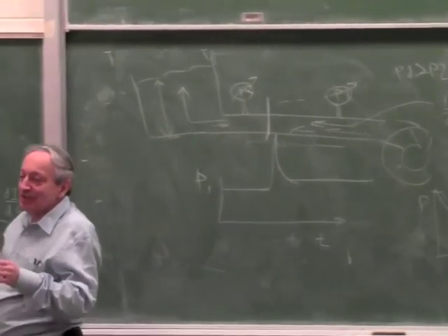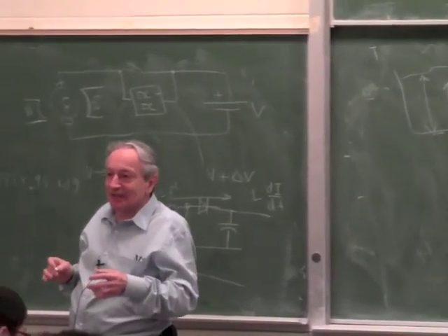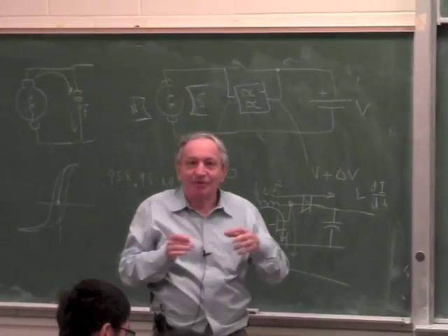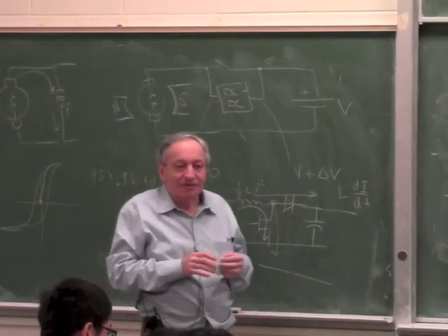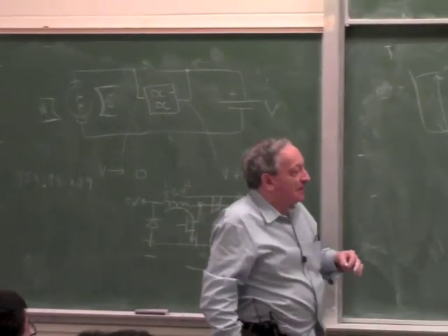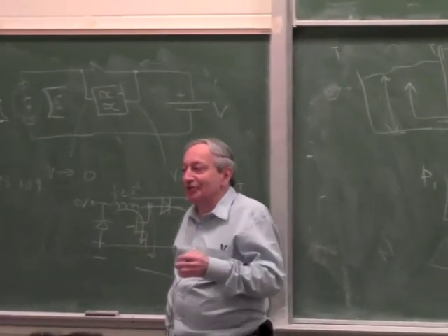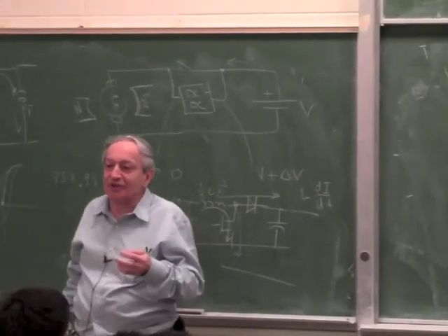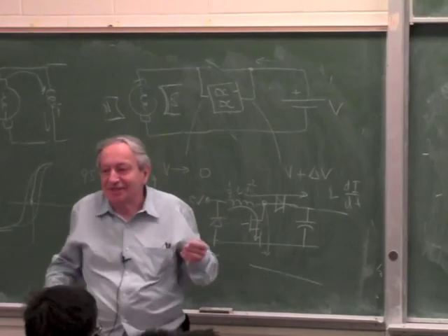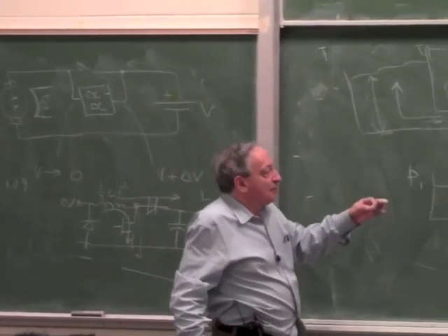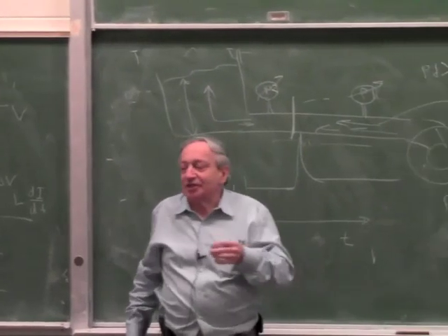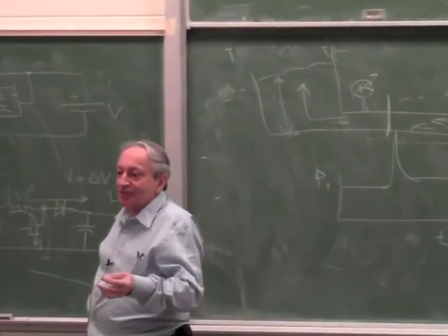If you understand them in one servo system like electromechanical, it only takes you a few minutes to apply it to a non-electrical servo. Okay? So remember again the analogy, because the only non-electrical servo you are likely to have to work on is fluidic. I mean, there's other things, but you're not very likely to work on them. So remember the analogy: in a fluidic servo, pressure is the same as voltage, flow is the same as current.